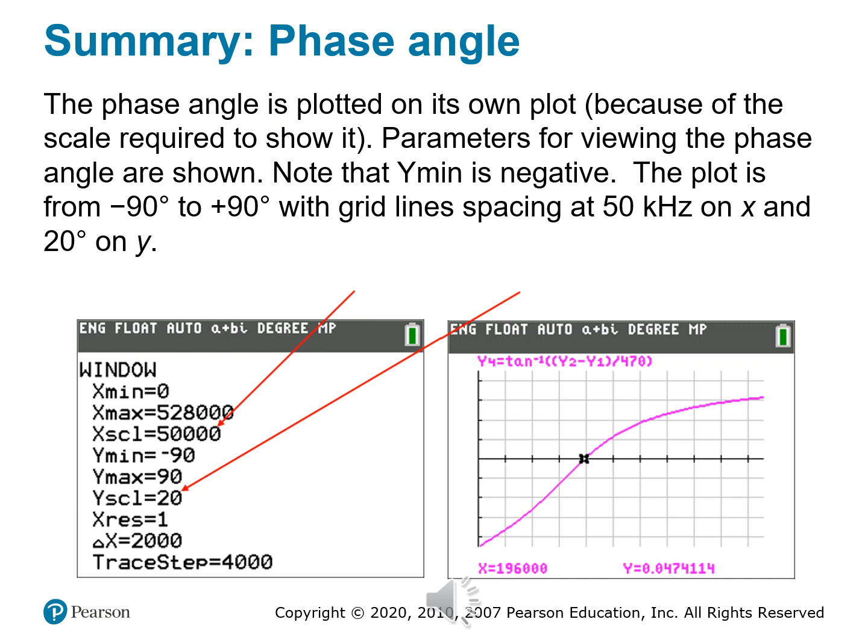On the right, on the slide here, you're going to see the actual curve plotted on the TI-84 Plus, and that trace cursor is sitting right at the resonant frequency, around 196 kilohertz. That's where our phase angle passes through 0. And again, you're asking, but why is this important? Well, because at resonance, the inductor and capacitor cancel each other out. Again, the Oracle was right the whole time. She knew that. And the circuit's behavior becomes purely resistive.